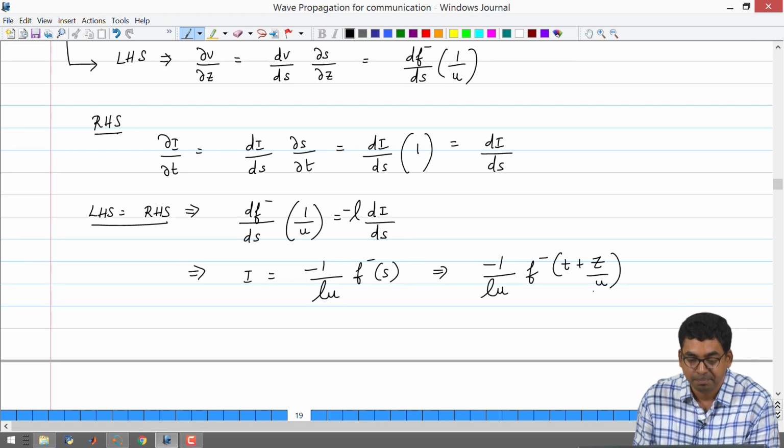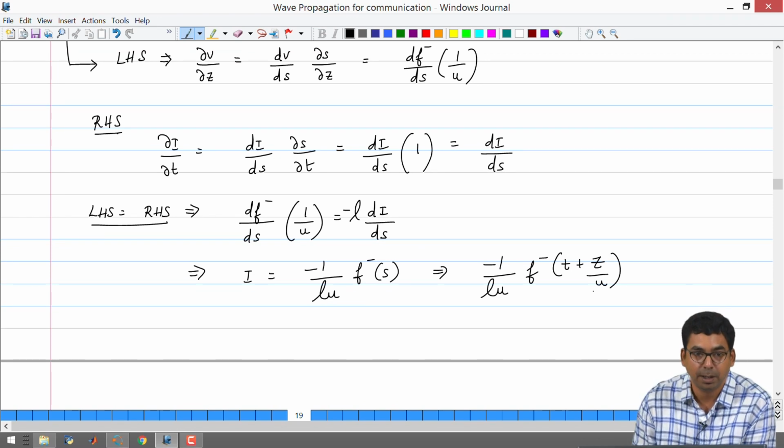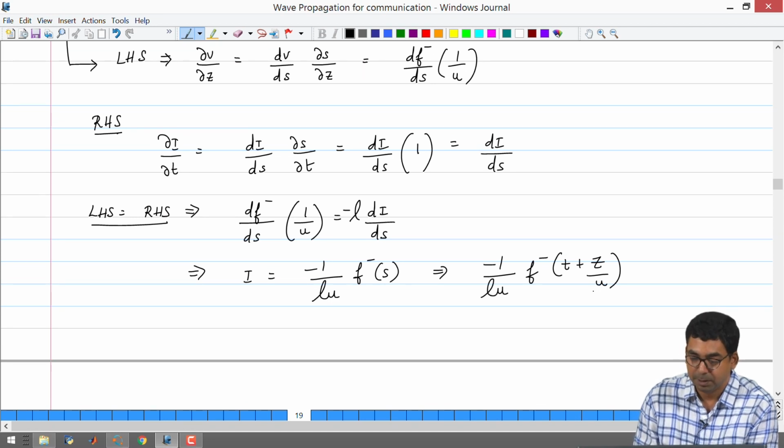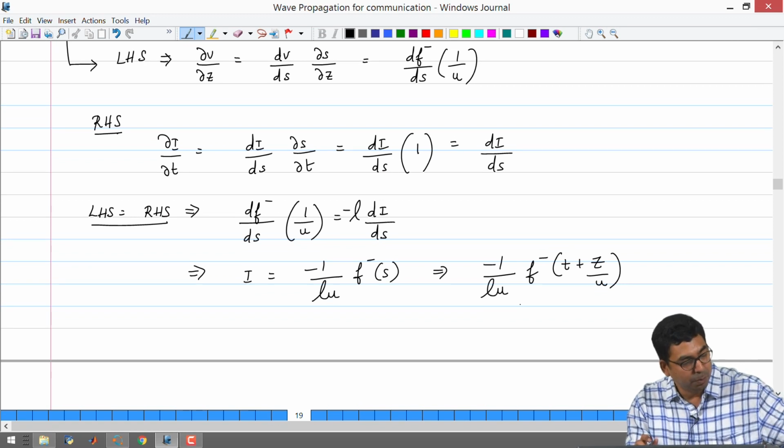Okay. So here it is abundantly clear that if you have a backward travelling voltage wave, the method of calculating current is slightly different. Okay. Since we are looking at this equation in the form of Ohm's law, you can say I is equal to V divided by R, but it looks like it will have the unit of characteristic resistance, or ohms, but you are going to have minus 1 divided by Rc, or characteristic resistance, multiplied by the voltage, right.